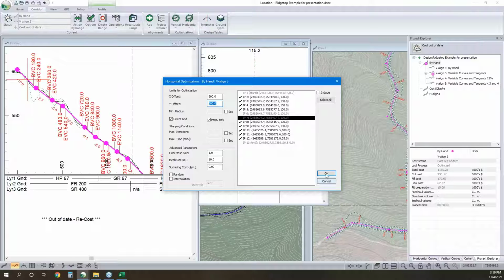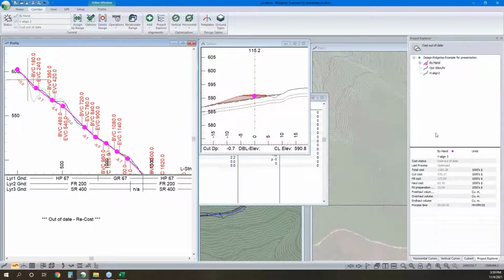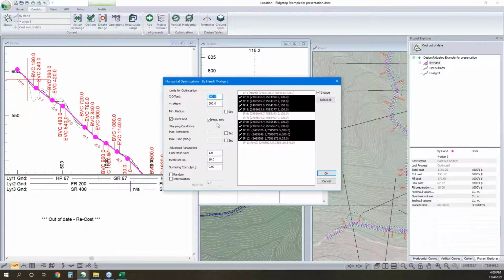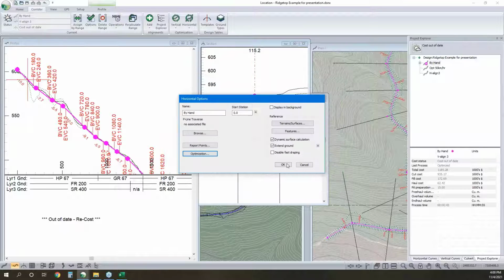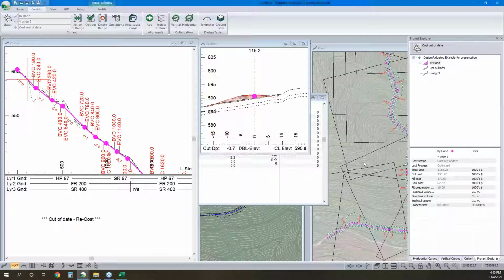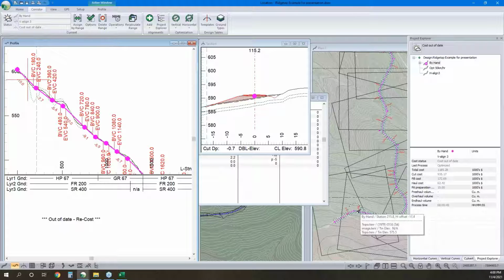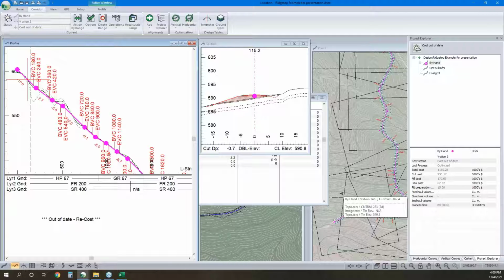And then, when we tell the software to do its thing, we want to turn that off. So we've got these big boxes where our IPs could be moved to. We tell it to run. The horizontal optimizer uses the vertical constraints, and it iteratively adjusts the horizontal IP locations to find a better position for them.